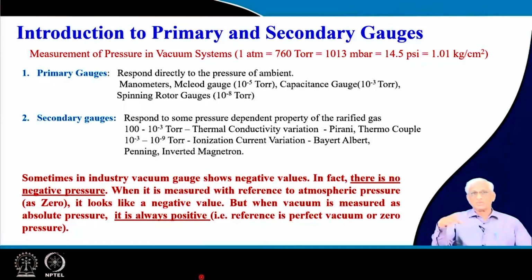Okay. So, when they do that, normally the gauges they connect to the system measure the high pressure, because the compressors are at high pressure. But during this purging or refilling, we are evacuating the whole thing. That time we also need a gauge which measures vacuum.